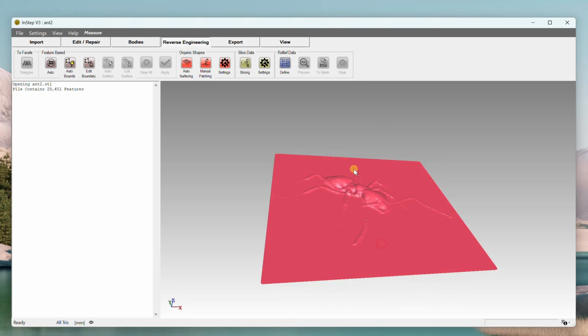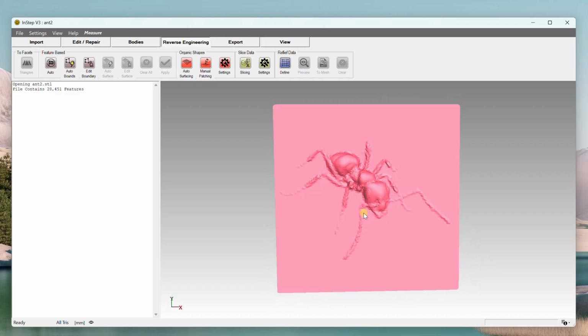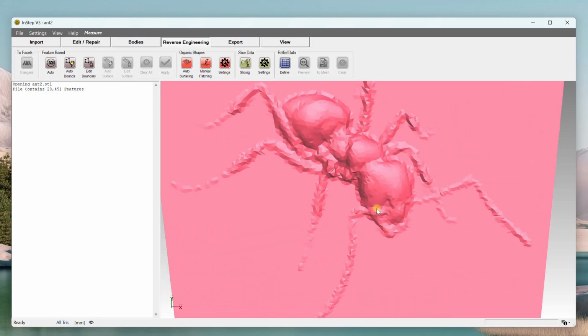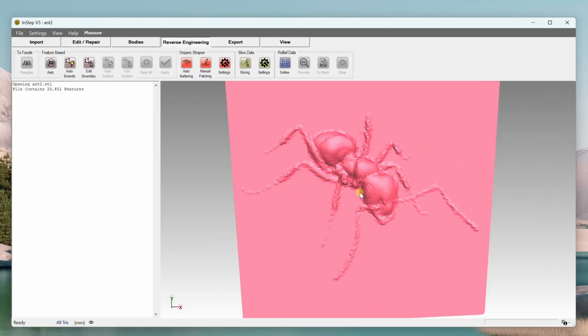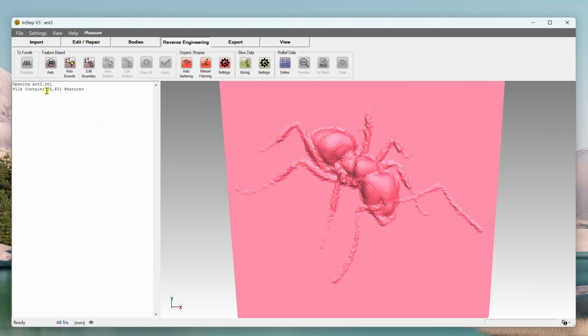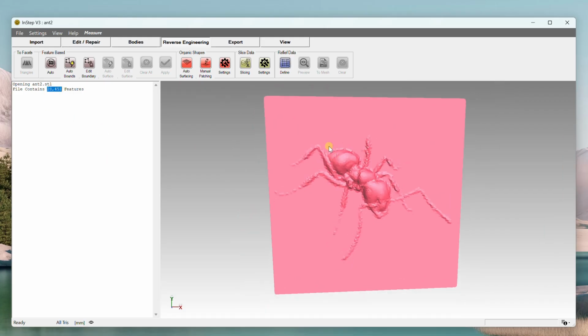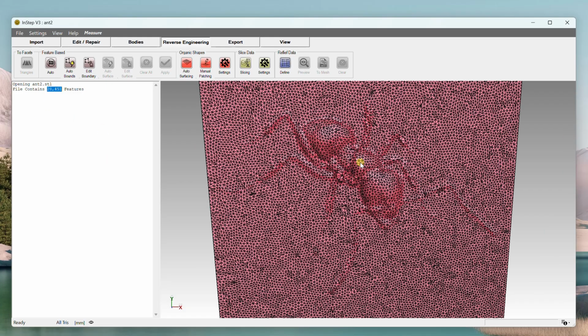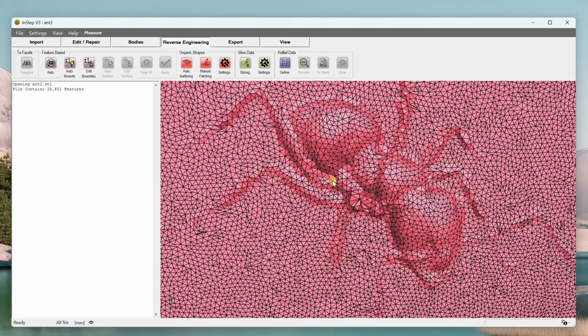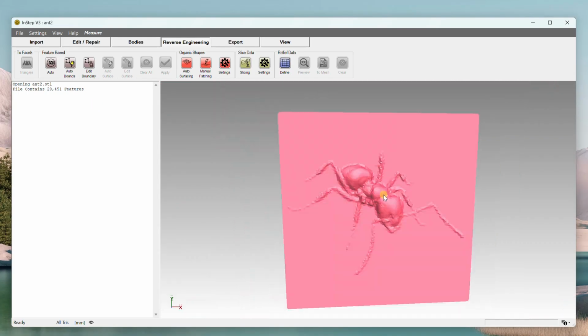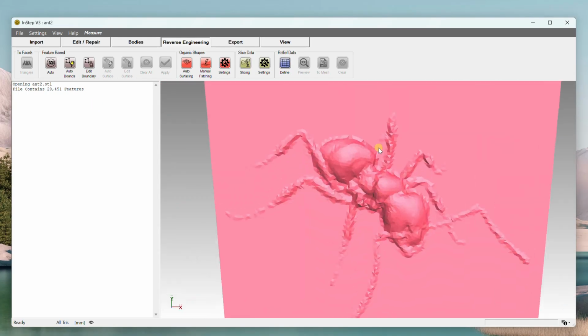The most likely scenario is topographical maps, or cases like this. This came from a software called Relief Maker, specifically for that. And this is already a reduced data set, so it's only 28,000 facets. If we look at the edges and turn those on with Alt and E, we can see it's relatively coarse. The reason behind that is just I want to keep this tutorial relatively short.